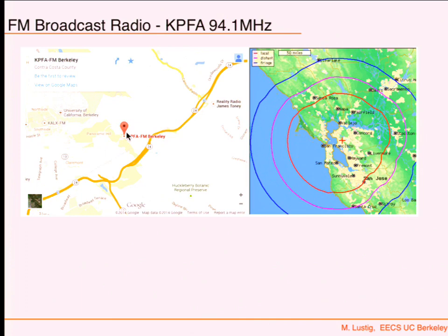So again, like every other place, please do things closer to a window or outside, because that's where things are being transmitted. Especially if you're going to use the small antennas that we give you, they're not that efficient for FM. FM wavelength is 3 meters. This is not a half wavelength antenna or quarter wavelength antenna. So they're much smaller, so they're not as efficient.